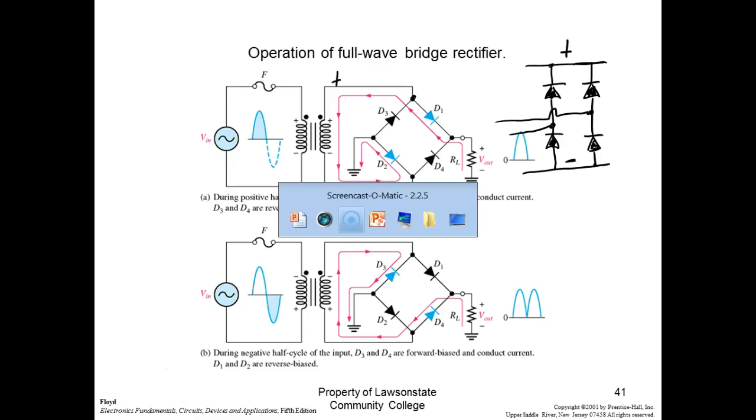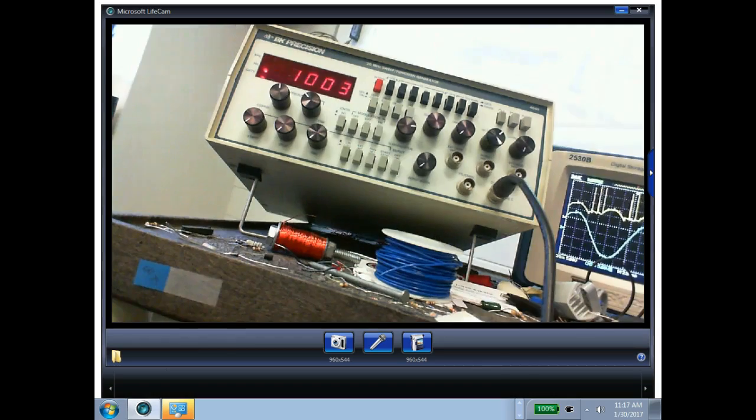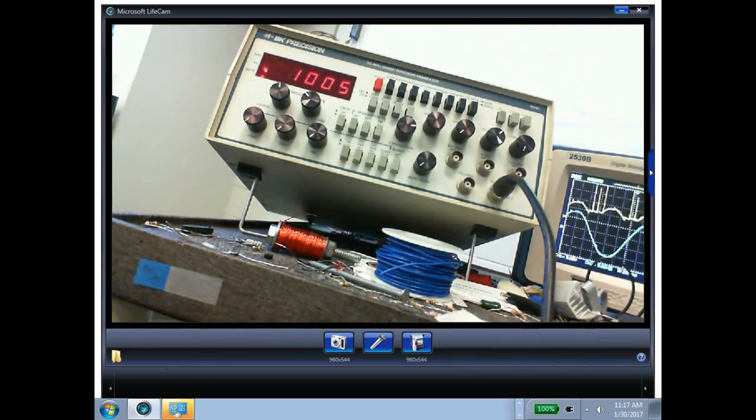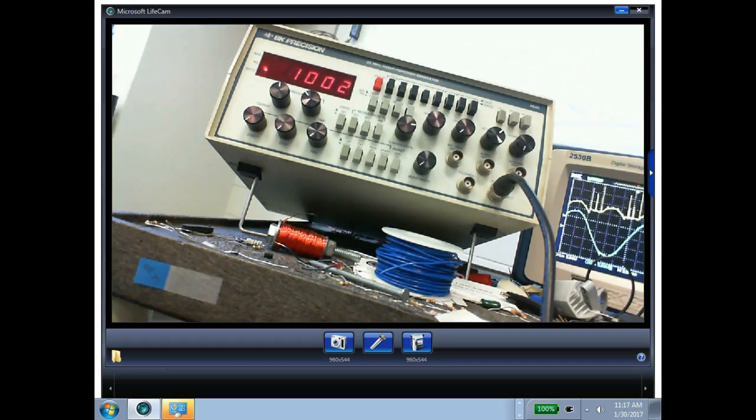So we call this a function generator. Now what's neat about a function generator is that it takes power in, then they run it through a power supply that somehow gives us a plus and minus DC. Right? You understand? And then now they can regenerate an AC, but now we can control the amplitude and we can control the frequency because it's done electronically. So yeah, this guy here has a negative and positive supply in it.